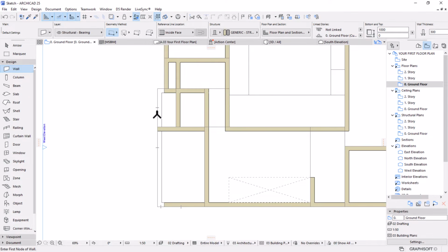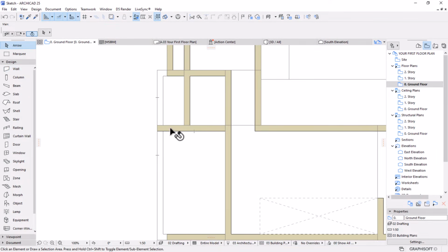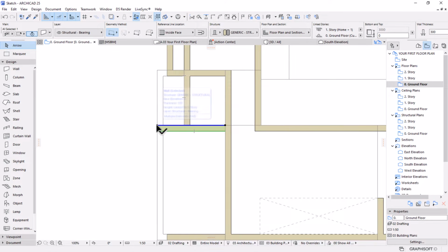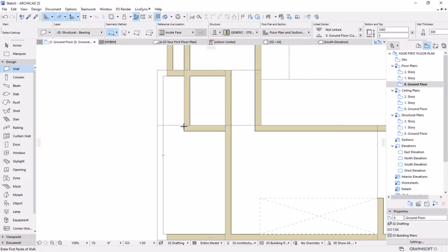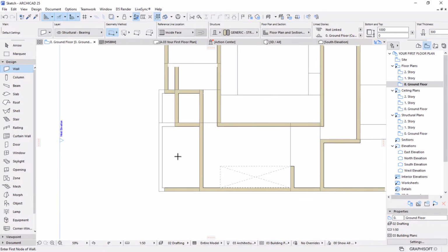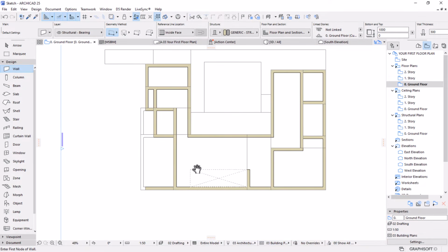Perfect. We have this little kind of a thing. We have the same situation for this wall as well. Let's take this wall. I think it has to be chamfered with this or filleted with this one. So let's hold shift and add selection for these two walls, then come at the top there and intersect. So I'll pick parameter of this wall, then place there. It's wrongly positioned. Let's flip it by clicking on this icon, then perfect. So that's basically how you maneuver and play around with your wall settings.